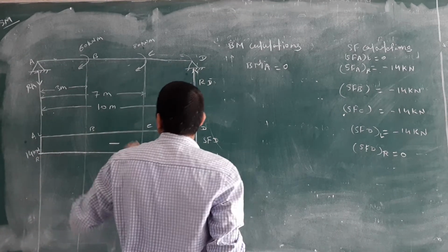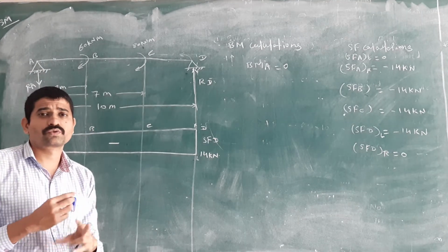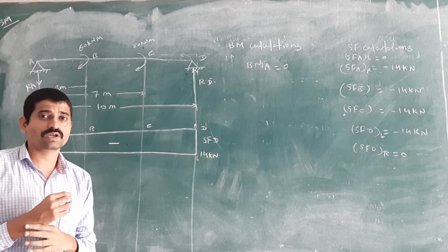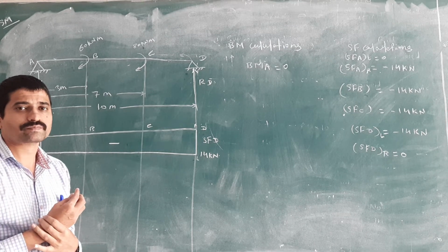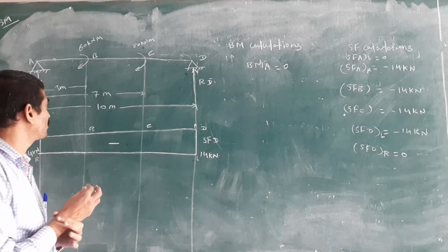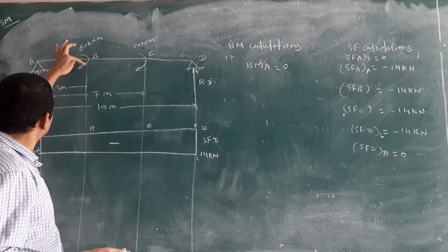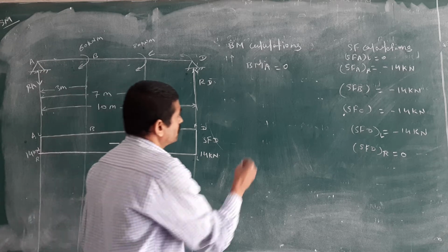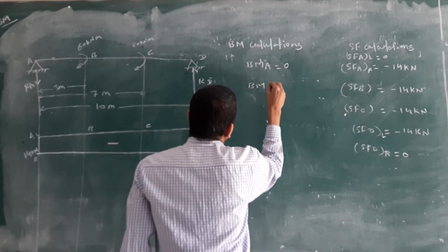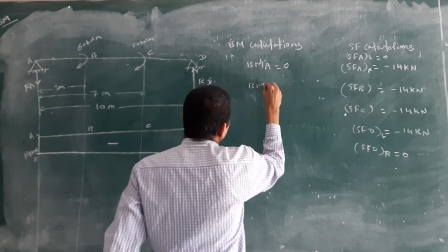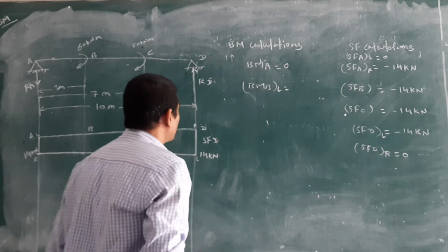Okay. Then where the couple is at that point, you will get 2 bending moments. One is the minimum and one is the maximum. Remember that. Okay, reverse of that SFD. Here where the couple is in the bending, you will get 2 points. Then how to write those 2 points? Bending moment of which point? B point. Just left side. What is the value of that?